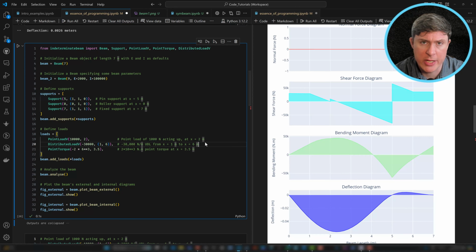Algorithms can manage intricate decision-making processes. Think of optimizing your beam design. An algorithm can iterate through standard sizes or geometric configurations, assess each against stress limits or weight, and if any of these options fails the check, the algorithm can have rules in place to discard a certain size and move on to the next check by increasing the beam depth or web thickness or some other predefined parameter.